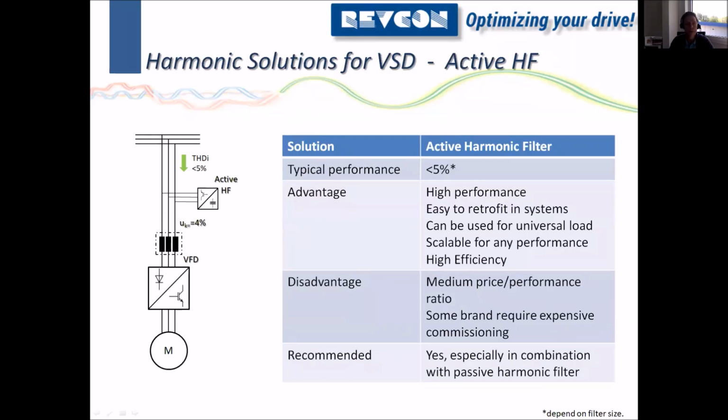So you could make some kind of power factor correction. You could handle harmonic distortion, and you could even solve unbalance in your system, which I don't recommend to do this way, but you could solve unbalance with these units. That's the benefit of an active filter. It's typically more expensive than a passive filter, depending on the size, because you can use an active filter for many, many small drives. But yeah, that's the main thing.